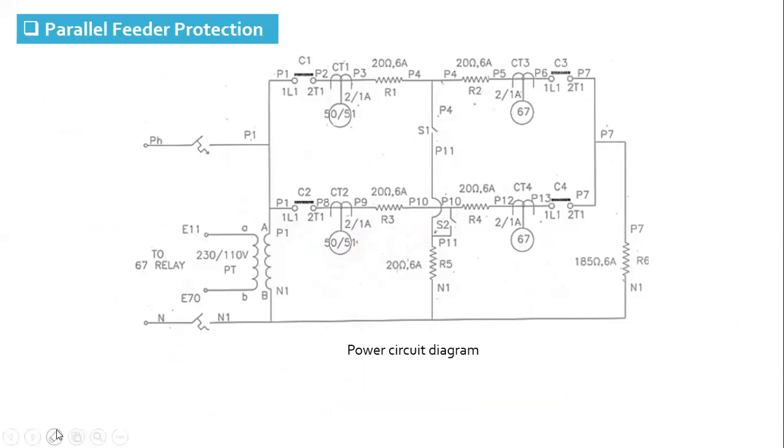Just like the control circuit we have discussed previously, first we will close breaker 1, then we'll close breaker 2. So line 1 will be on, and the total current on this line will be 1.12 ampere. Then we'll switch on line 2. So total current will be the same, but it will be divided into two parts, 0.56 ampere and 0.56 ampere. So that is a parallel operation.